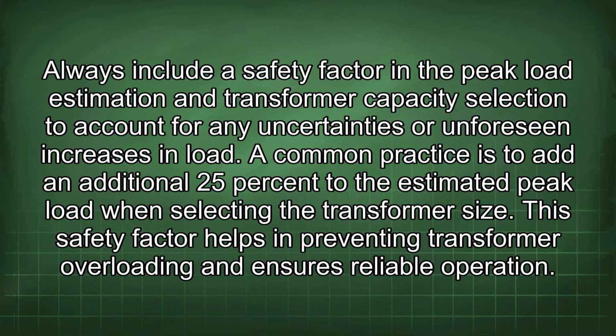Always include a safety factor in the peak load estimation and transformer capacity selection to account for any uncertainties or unforeseen increases in load. A common practice is to add an additional 25% to the estimated peak load when selecting the transformer size. This safety factor helps in preventing transformer overloading and ensures reliable operation.